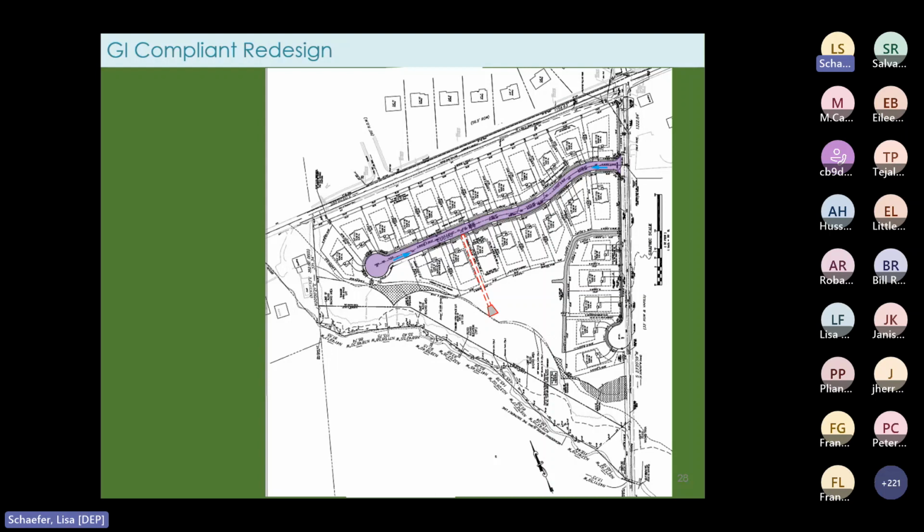All right, for my second idea, I would make the internal roadway pervious pavement. The BMP manual indicates that the maximum ratio of additional inflow contributory drainage area to the surface area of the pervious paving system is 3:1, and in this case, we should be okay. Now, the lawn areas would have to be regraded to drain away from the pervious pavement, maybe towards that perimeter bioswale that was on the previous slide.